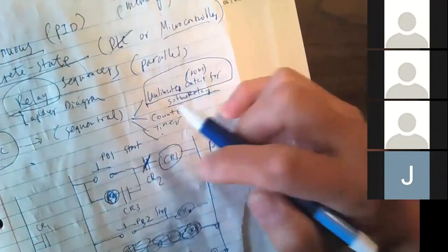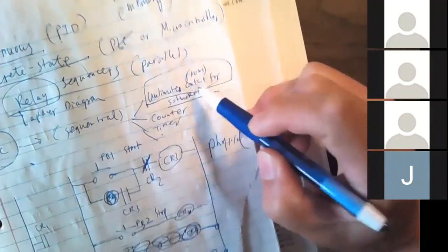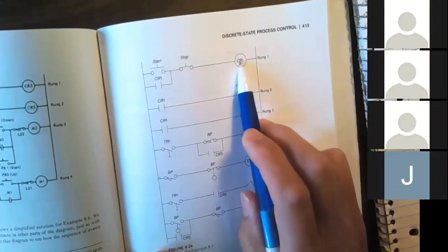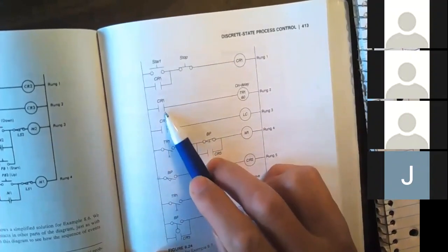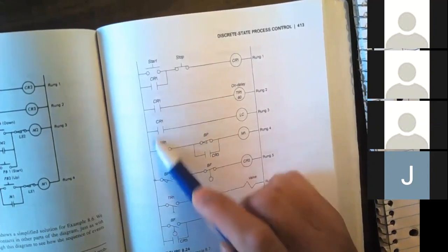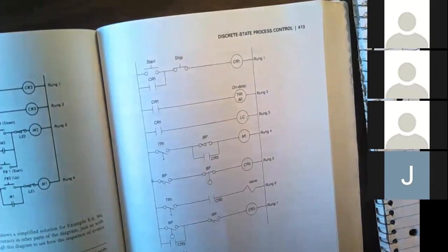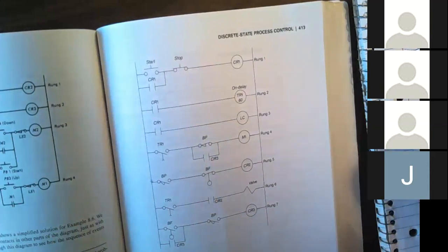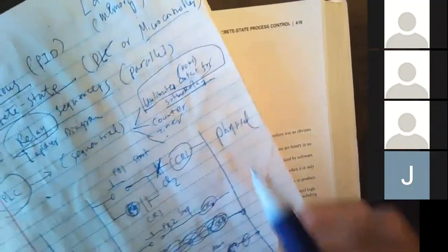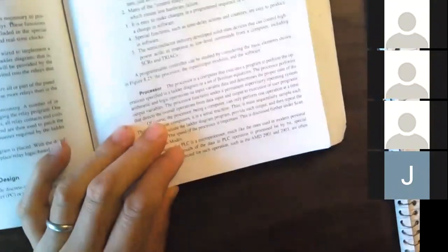And also each relay can have unlimited contacts. That's relay number 1, right? Relay number 1 physically has a limited number of contacts. Some have 4, some have 1, some have 2, some have 3, for example. But when we use a PLC to simulate relays, it's just computer memory. As long as you have enough computer memory, the number of contacts is unlimited. So that's the advantages of a PLC.